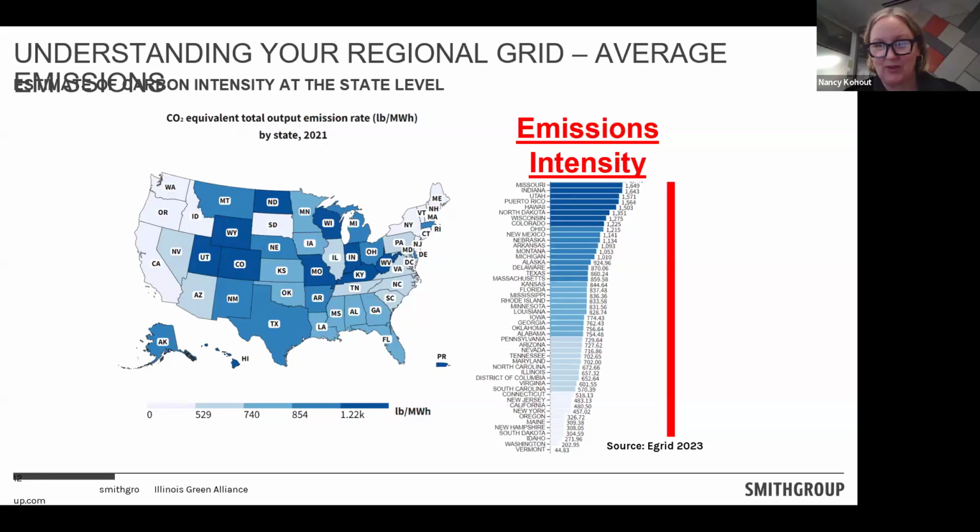Another thing we also have to think about as we think about utilizing heat pumps and going towards electrification is the carbon intensity of our power grid. And that's changing by the day. Grids are greening, but as you do an analysis to understand what makes sense for a project, it's important to understand the carbon intensity of the power grid. Because on a really dirty power grid, an air source heat pump, even though it's twice as efficient as electric heat, might not be more efficient when you consider how dirty the power grid is. And you might really need to consider water source. Next slide.